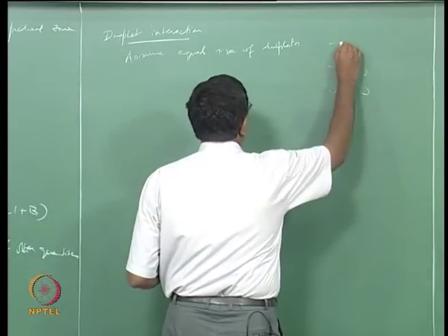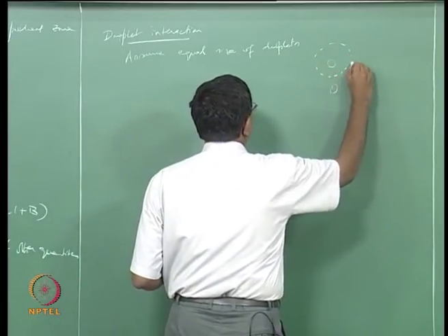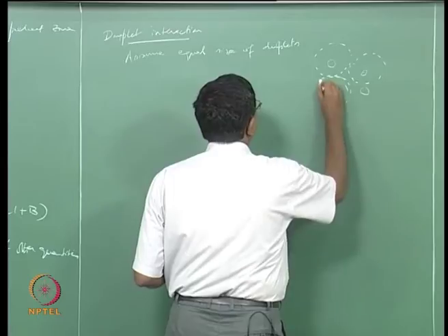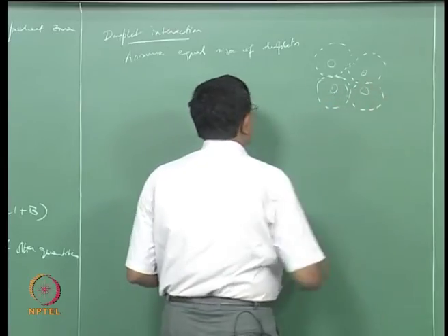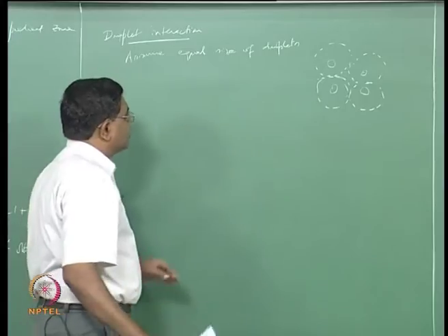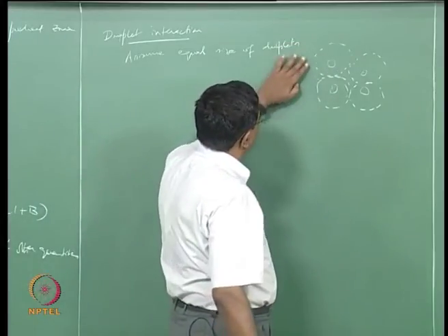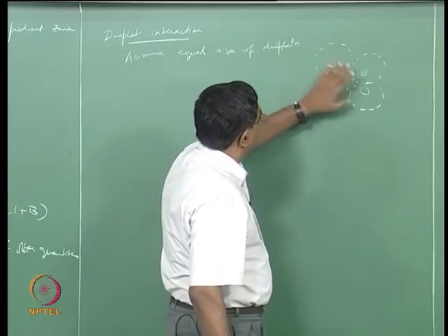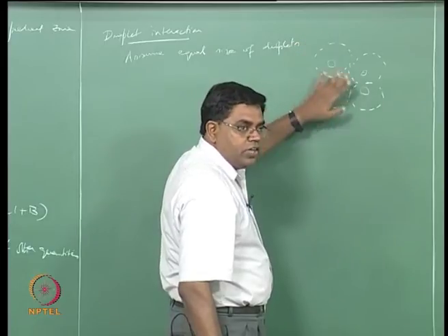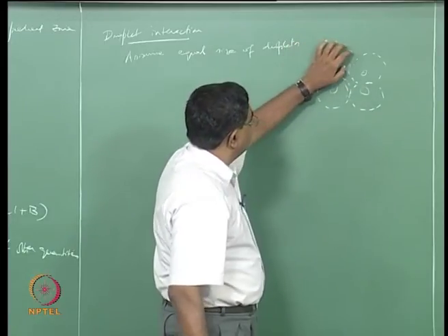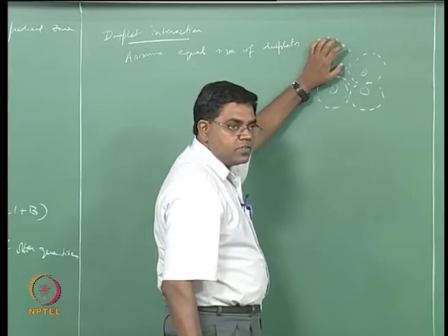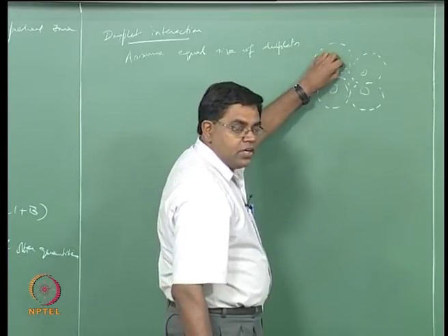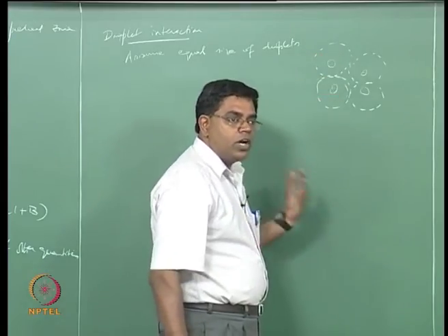So what we could then do is draw spheres around these, and if you say the sphere around the droplet that you have drawn has a diameter approximately equal to the interdroplet distance, and then you take that sphere worth of mass of oxidizer, neglecting the presence of the droplet, and take the mass of the droplet, you can now form a fuel air mixture based on that.